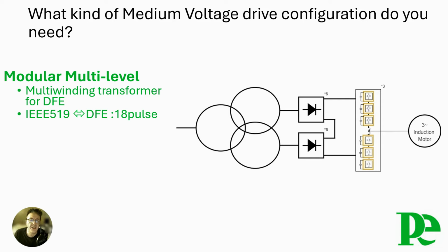Instead, each power cell within the inverter part has its own capacitors. This design results in improved fault behavior thanks to the low energy level stored in each cell compared to other drive topologies. A basic power cell consists of 2 IGBTs and 1 capacitor bank. Medium voltage levels are achieved by combining the outputs of multiple power cells.